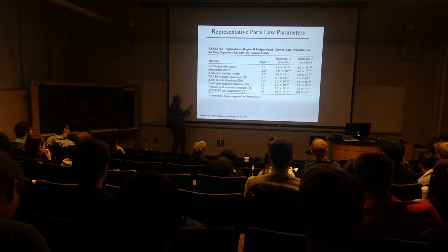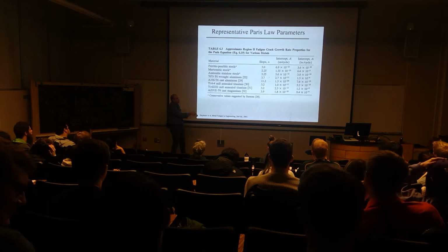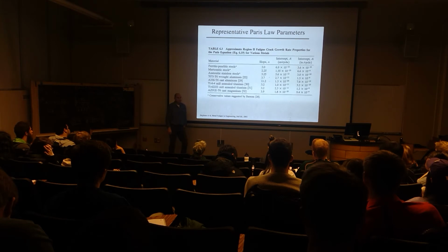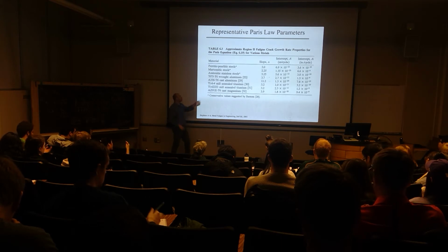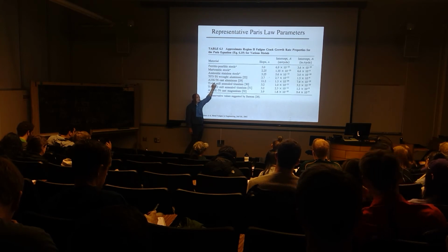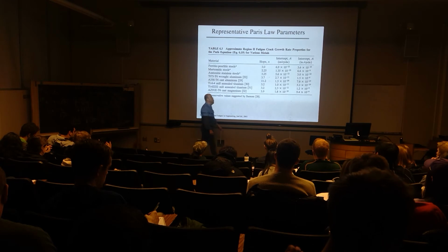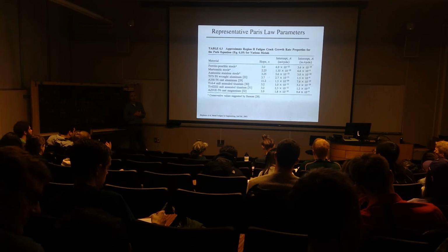So if I look, I have one material here, this A356 T6 cast aluminum. You can see that its slope says that the Paris law exponent is 11.2. What does it tell you about that material? Very sensitive to cyclic crack growth in comparison to those wrought metals. Definitely true, and we find that in general, cast materials, aluminum alloys, and magnesium alloys are relatively brittle. So indeed, this is a contributor, and their response is one in which those cracks are much more sensitive to cyclic loading and driving forces. So be aware of that.